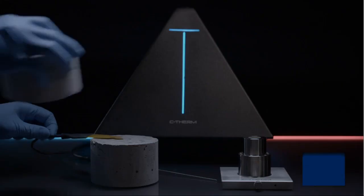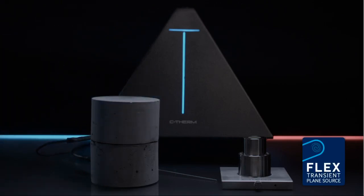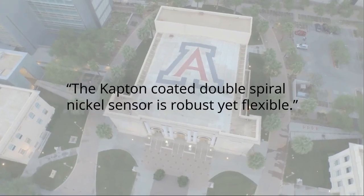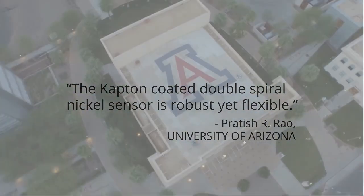With a double-sided sensor available in different sizes, the Flex TPS Transient Plane Source method provides researchers the greatest flexibility over experimental parameters, including timing and power. It is recommended for more experienced users, with specialty slab, anisotropy, and thin film modules available. With no contact agent required, the hot disk-style TPS sensor is ideally suited for polymers, compacted geological samples, metals, concrete, and asphalt. Flex TPS is ideal for experienced researchers looking to push the boundaries in thermal conductivity.